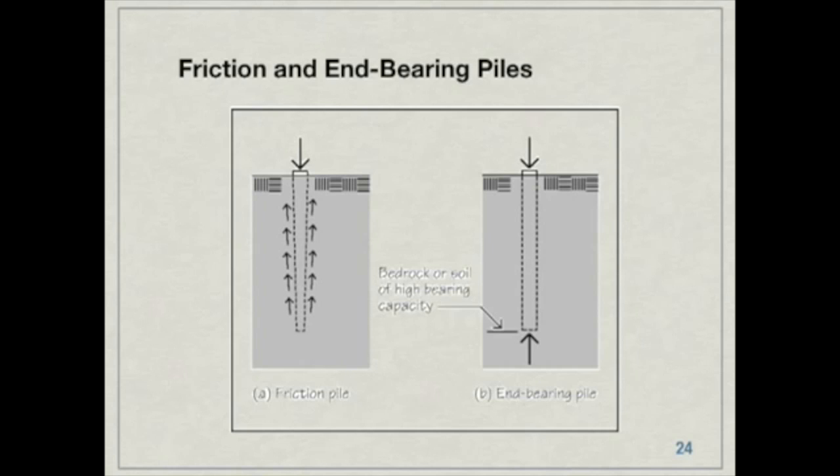Now also, because piles are generally smaller in the cross-sectional area, typically piles are not used solo, whereas piers can be. Typically piles are clustered together and then they are finished off with what's called a pile cap, and you can see this in the next slide.